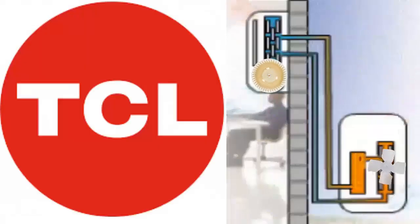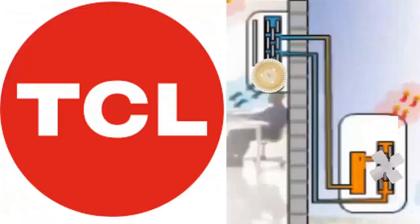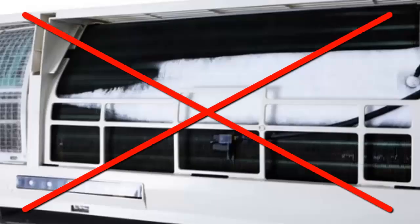The error E2 code in TCL air conditioners is related to issues with a temperature sensor located in the indoor unit of the equipment. Specifically, we are referring to the temperature sensor of the coil or heat exchanger, also known as the well sensor. This sensor is responsible for measuring the temperature of the refrigerant inside the pipes of the indoor unit, with the primary goal of preventing excessively low temperatures and avoiding external freezing in this part of the equipment.